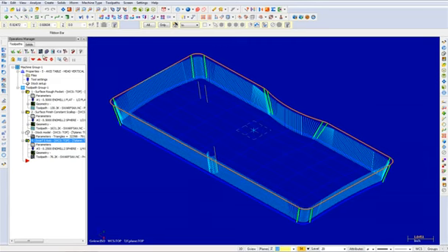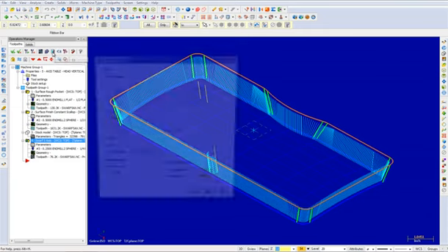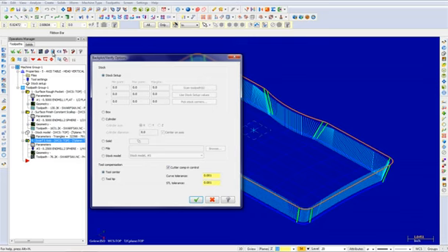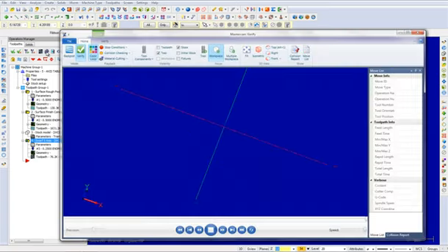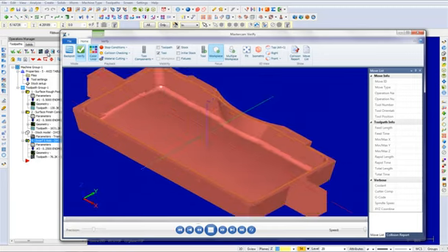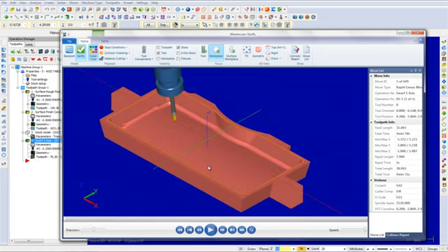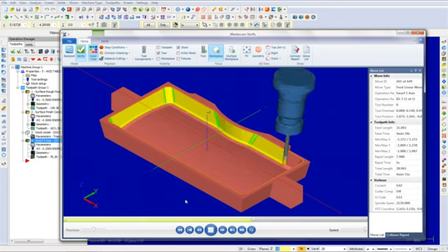Once the toolpath is generated, backplot and verify it. Select the backplot verify options first. Enable stock model. Choose the stock model that we created, then select the OK button. Then verify the part. Once complete, your part will appear as shown.